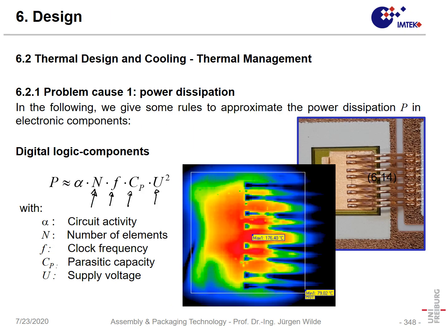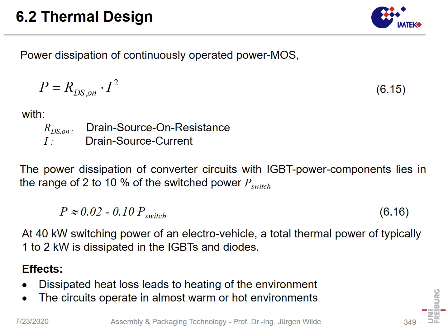Now let's go back, have a look at such IGBT transistors, and here we can see in such transistors we also have one gate which you cannot see here, but when the gate is turned on and off, that device is switched, and it is not so easy to predict the power dissipation in an IGBT power module, but we must say IGBTs are made for maybe 0 to 200 amps and typically 0 to 1200 volts.